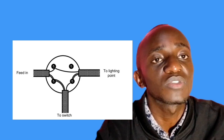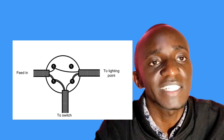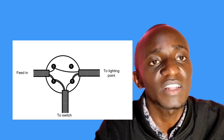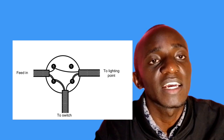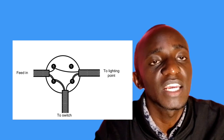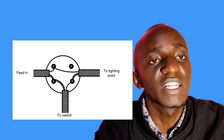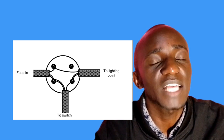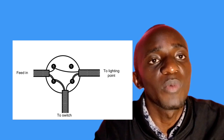We have said that a switch has two terminals, where one is the supply terminal, the other one is the load terminal. The supply terminal is the one commonly known as common, and the load terminal is written L in many switches. So that's how we do connection at the joint box.